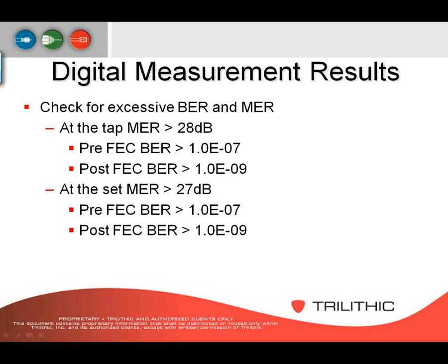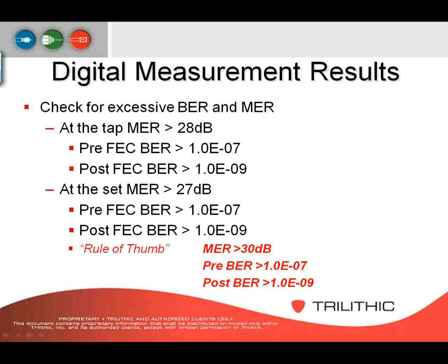So for your digital measurement results, these are just some industry standards for what you're looking for as far as your MER and your BER. At the tap, you want greater than 28 dB. For your pre-BER, you want greater than 1.0 e to the -7.